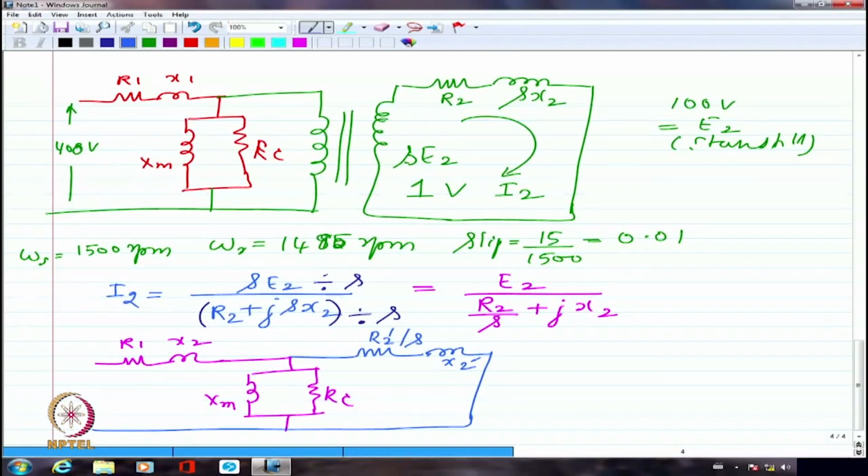But, this is X1. Right? So this is the overall equivalent circuit of the induction motor, where the resistance inherently, what was there was R2 or R2 dash if I look at it from the stator side, but I have divided that by S to take care of conversion from the rotor frequency into stator frequency. We have a little bit more of work to do on this equivalent circuit.